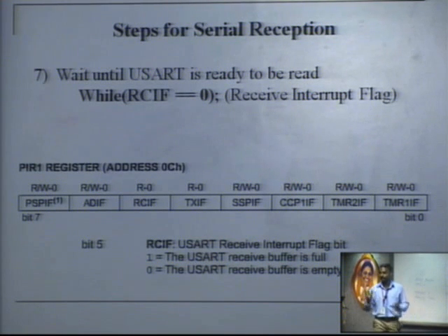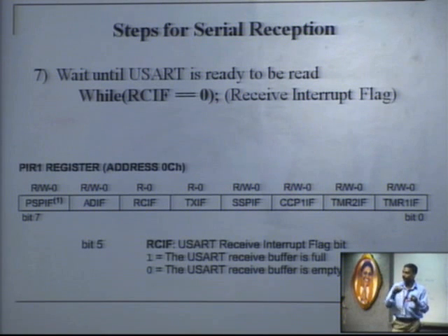So when the reception is complete, will the receive buffer be full or empty? Full. If you are receiving something on your plate, it will be full, no? So here, if the reception is complete, your receive buffer will be full. But in the case of transmission, if it is ready to be transmitted, that buffer should be empty. If it is empty, then only I can give some data. If it is full, then I cannot. If we have a pot and it is completely filled with water, I cannot fill it again. It should be emptied, then only I can fill it. So before transmission, you need to check whether that buffer is empty, that is TXIF equal to 1.